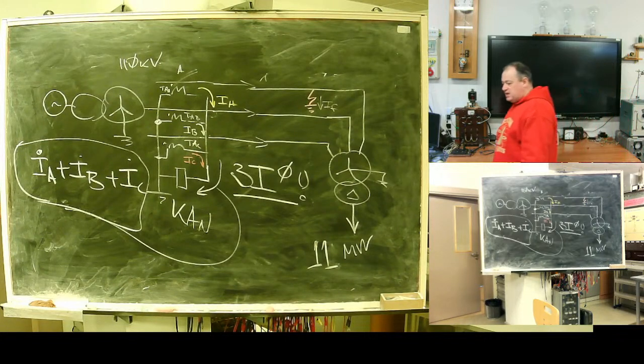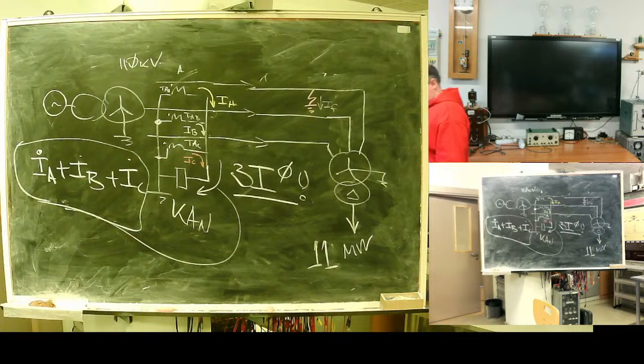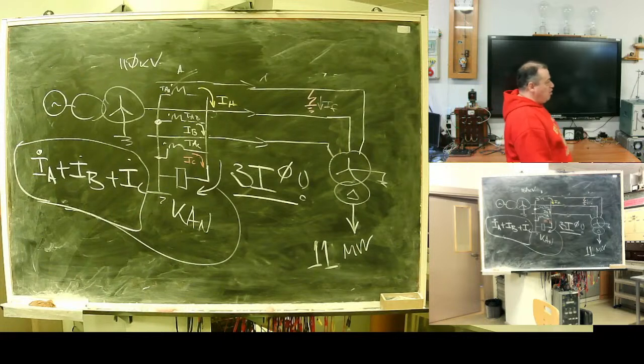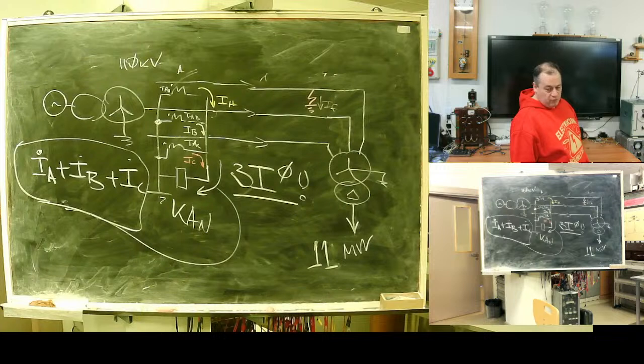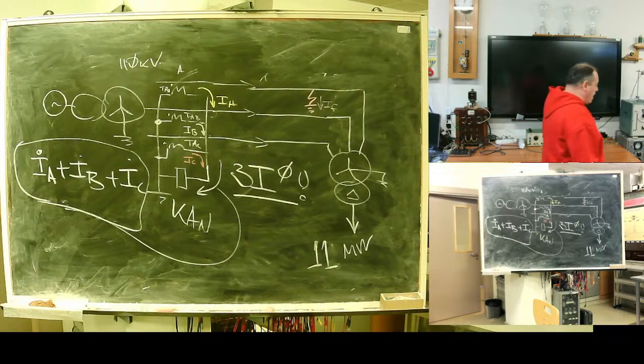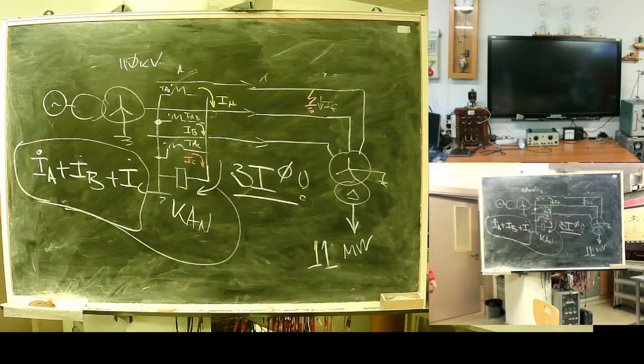For many years it was instituted by law as the main protection of Earth and ground high voltage network. Now it's also mandatory, but as a backup to primary distance protection. But it's still very reliable.